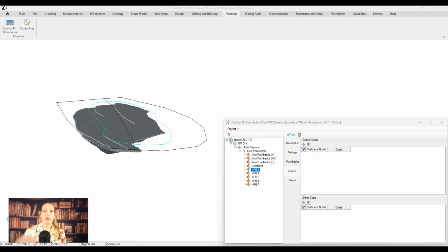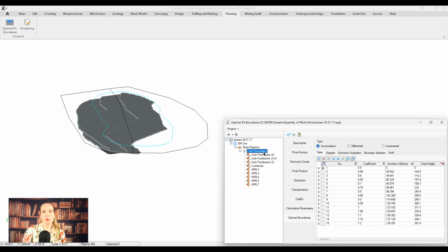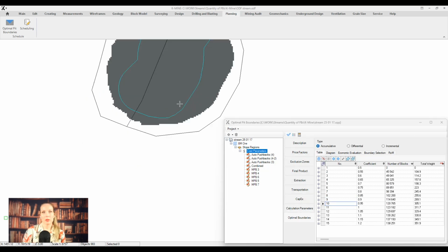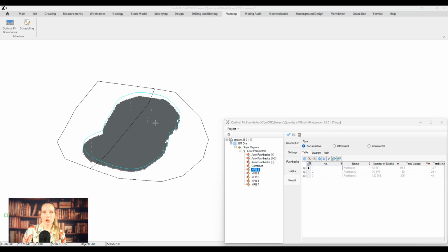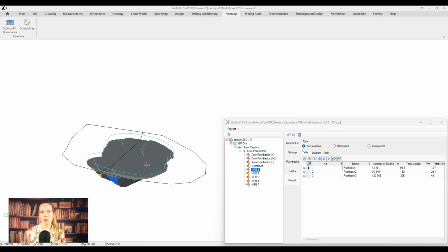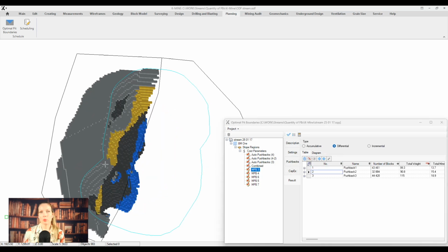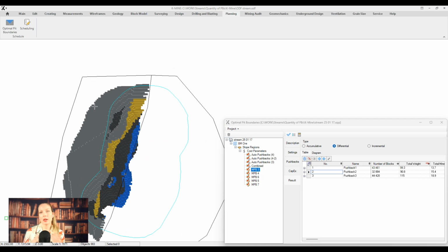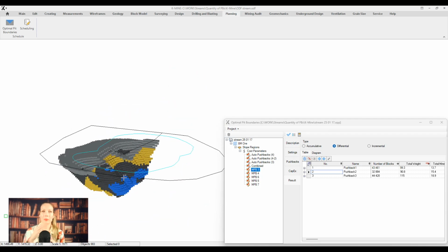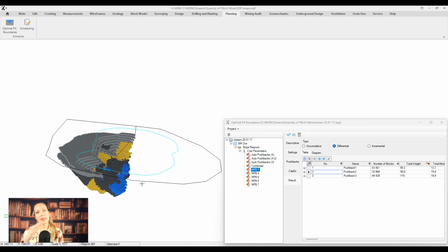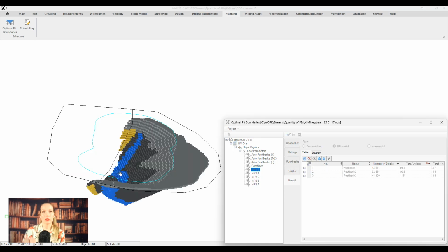Plus, you can decide whether to consider the connections between blocks calculated for angles or ignore them, which would include all blocks within the constraints. You set it up for each pushback. For instance, we've used polylines for all of our manual pushbacks. It's fine if the lines cross over each other, blocks won't count it twice, but if you're a perfectionist, you can make each new contour touch the last one, and that works too.